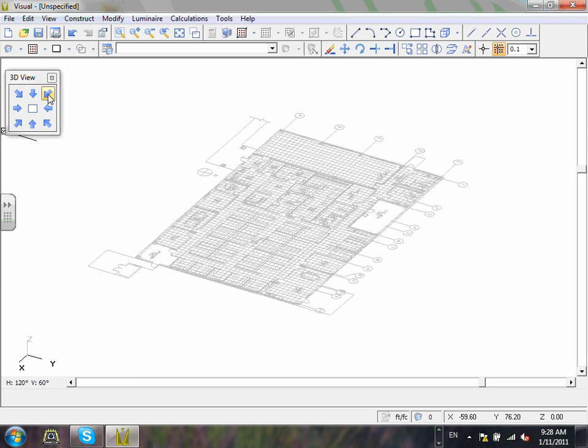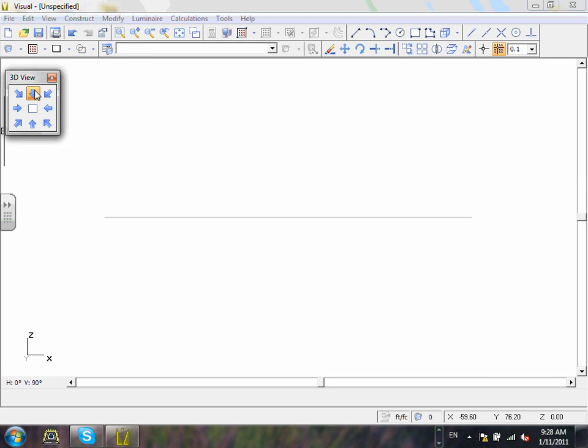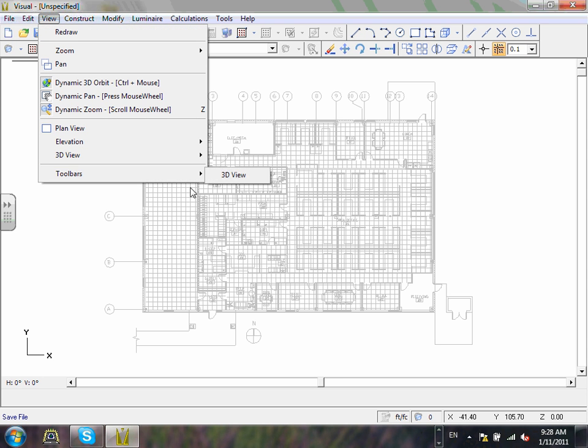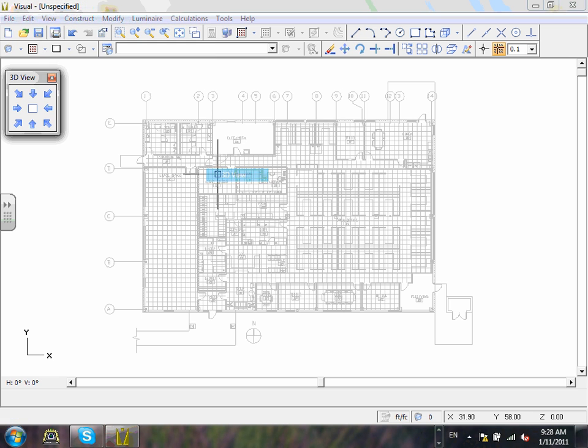These are very important because I'm going to ask you guys to print me a report based on southeast, southwest, north, south. So this is looking from the south, looking from the north, at the building. First there's nothing because it's 2D yet. So this 3D interface is a big deal. If you lose the 3D interface for whatever reason, no problem. Where do you find it? View, Toolbar, Toolbar 3D. Am I clear about this before we move on? Because later on I'm going to ask you guys to use this one. Step number one is done.